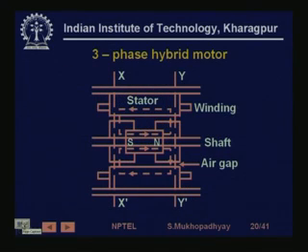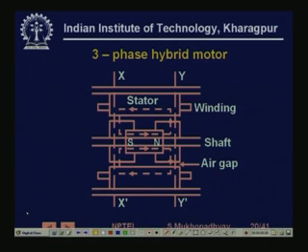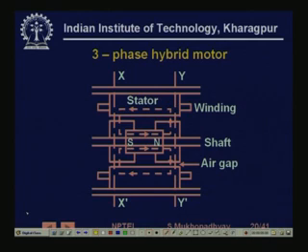Now, we worry about what else we can do to increase the resolution further. We have seen that the resolution depends on the stator pitch and the rotor pitch and the difference between them. Now there are various concepts. One of the concepts is what is known as a hybrid motor.